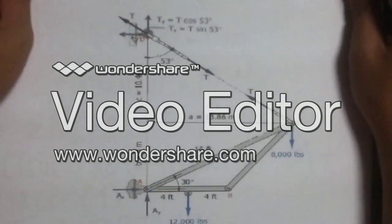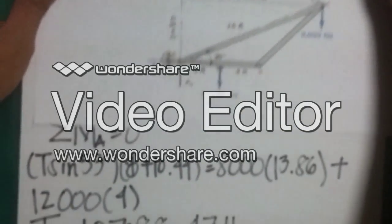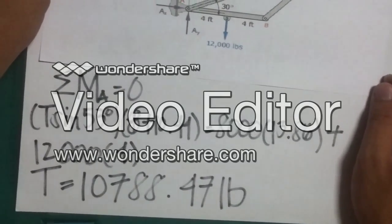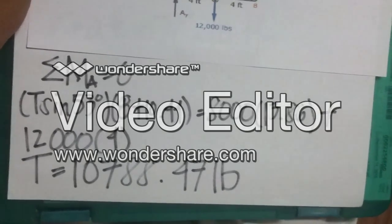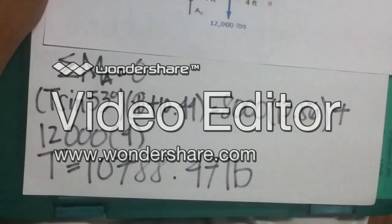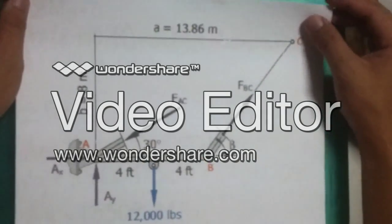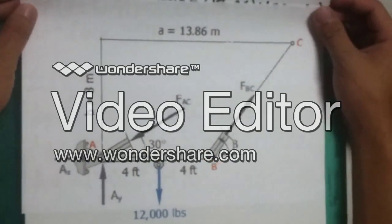To find the tension on cable CD, we take the moment at point A, and the summation of moment at point A is equal to 0. So T sine 53 degrees times 8 plus 10.44 is equal to 8,000 times 13.86 plus 12,000 times 4, and T is equal to 10,788.47 pounds.